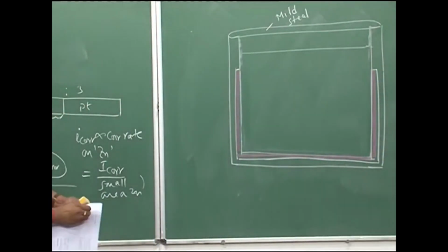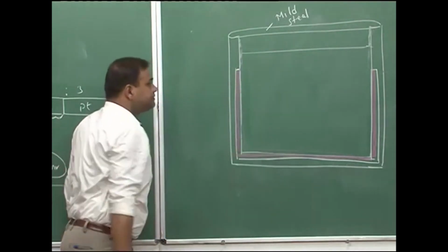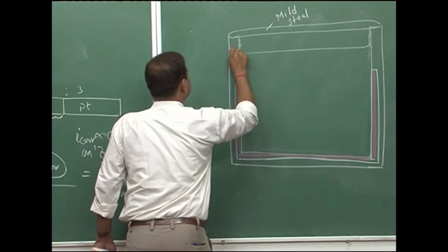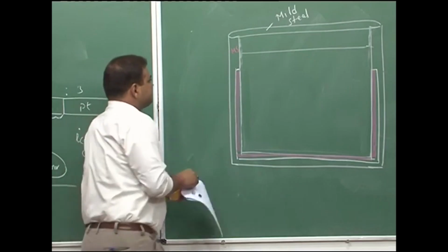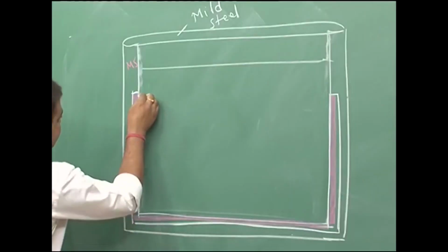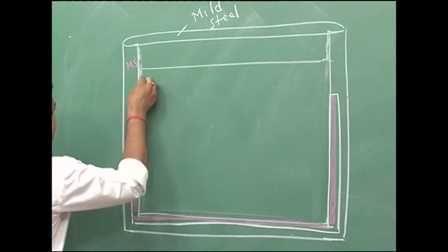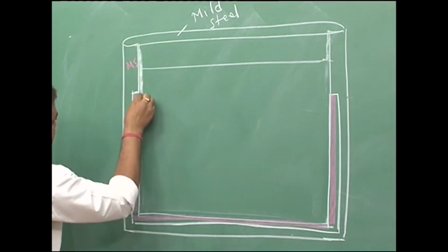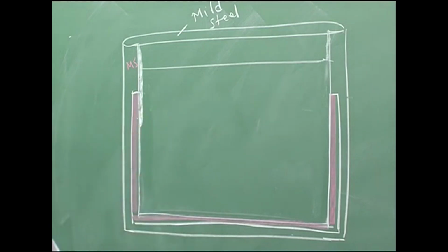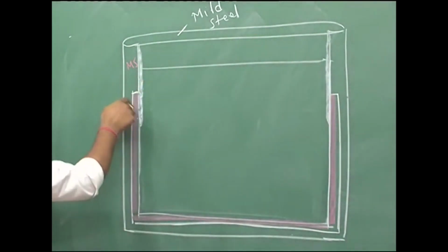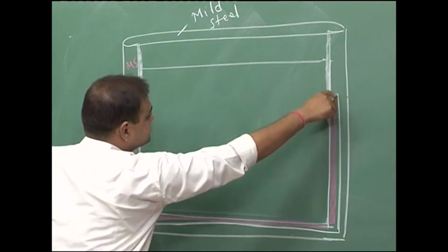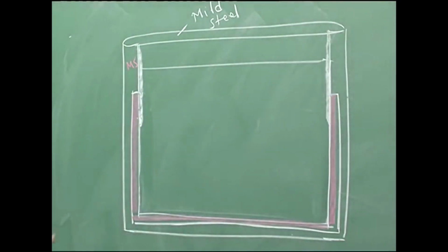This bottom part is made of stainless steel, basically stainless steel clad, and the rest is mild steel. Since this is a contact between stainless steel and mild steel, we extend this phenolic coating up to a certain distance from the bottom, just to avoid the galvanic effect at this zone, since mild steel is anodic and stainless steel is cathodic as well as noble in the galvanic couple.